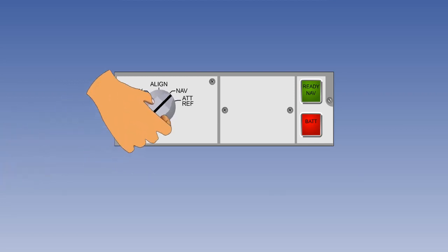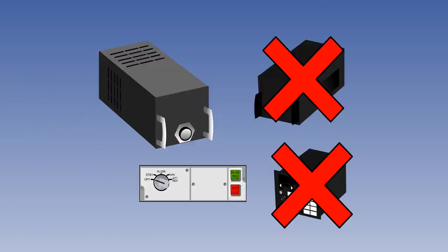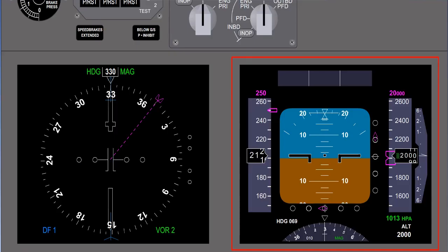We now come on to the attitude reference function. There may be occasions when full navigation computing is not available, but the gyros are serviceable. This could be in the event of a computing malfunction so that Earth rate and transport wander corrections cannot be calculated, or it could be after an alignment failure in flight. On many aircraft, the gyros are used as primary attitude information, as well as for inertial navigation, and it may be possible to retain gyro information.